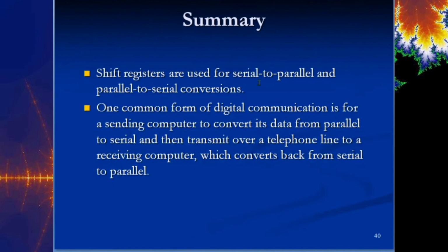So just to recap, shift registers are used for serial to parallel to serial conversions. But somewhere lost in that is the fact that the whole purpose of this is that we're trying to get data from one place to another in an orderly fashion. We can load it into a register and either hold it there until we need to move it, or we could load it in and immediately start moving it, depending on how we have our system set up.